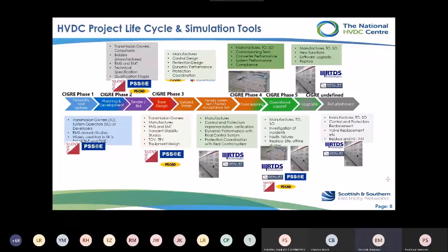We then move into a factory acceptance environment where we are well used to hardware being introduced into the loop and an RTDS framework being utilized as a testing platform for the real responses of a control and protection system to sample disturbances, which may inform a code and indeed compliance requirements based on those generic disturbances.